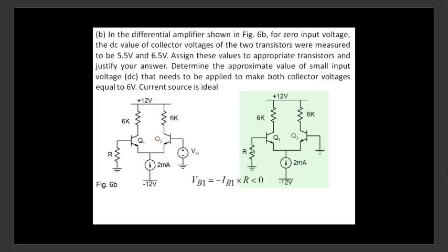Okay. Now, this is important because many times what happens is, I may have applied a signal from here, and the signal has some resistance with it, RS. So I'm applying a signal here from this point, and the signal has some resistance with it. And so apart from Vs, the signal resistance will cause a distortion, will cause more current to flow here or less current to flow here.